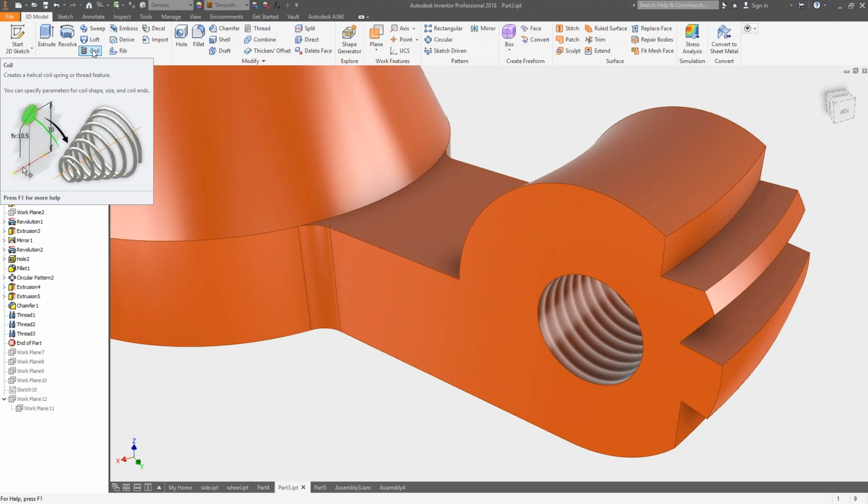When you think about the complexity of a real threaded helical cut through a component, and then let's say you have lots of those, and then you build an assembly, that's why traditionally I never ever do real threads inside of a model. These threads here will show up inside of your 2D drawings. They will be automatically called out with hole and thread notes. So for all intents and purposes, it does exactly what you need it to do.